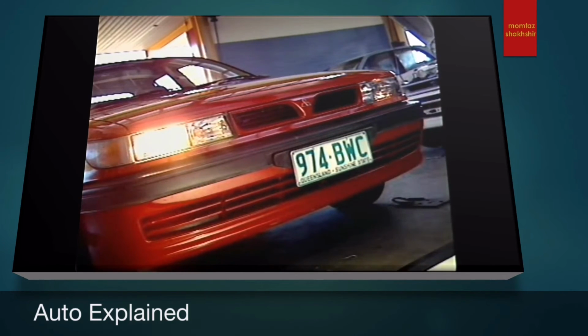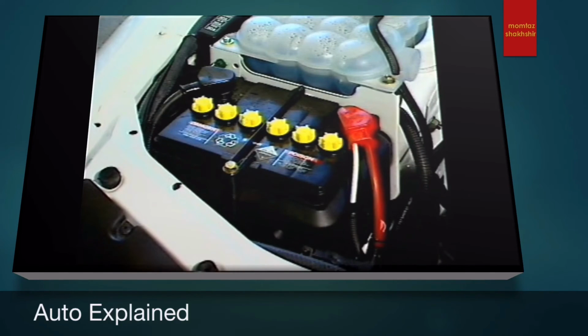Also, since all components connect directly to the battery terminals, the metal of the vehicle's body can become one of the conductors. One terminal of the battery and one of each component can be connected anywhere on the body or chassis to complete the circuit. This is called an earth or ground connection. It saves a lot of connecting wire.